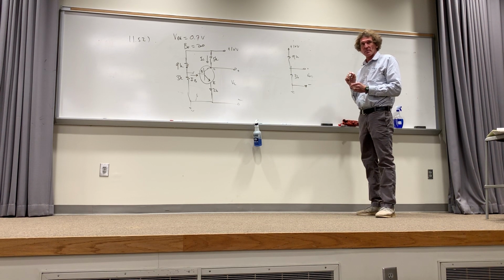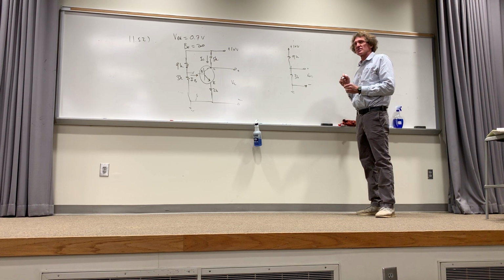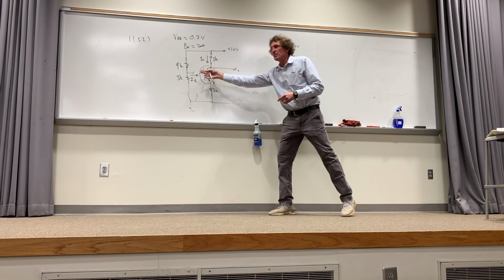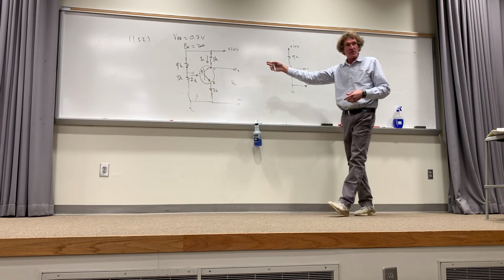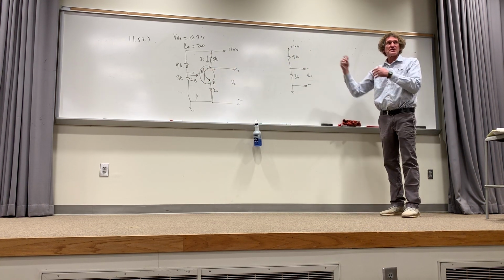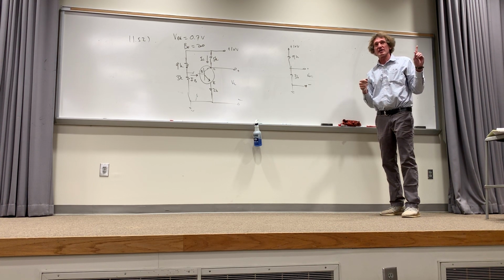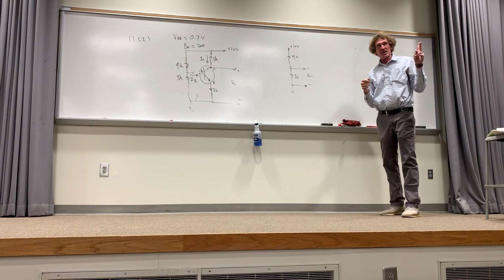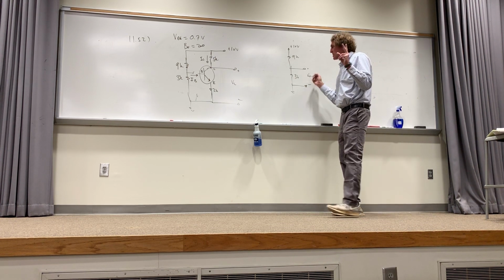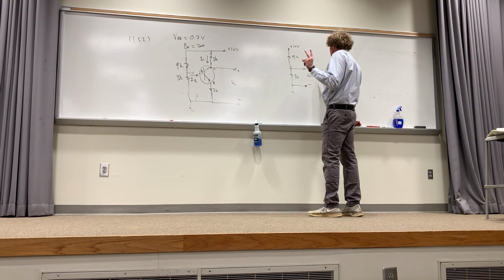Think about this. This is a Thevenin circuit, right? We're going to connect this stuff to it. But to get the Thevenin circuit, we first disconnect the load. Do you remember that? You identify the load, then you take it out. That was the first step for Thevenin analysis. Do y'all remember that? Second step was what? Finding the open circuit voltage.